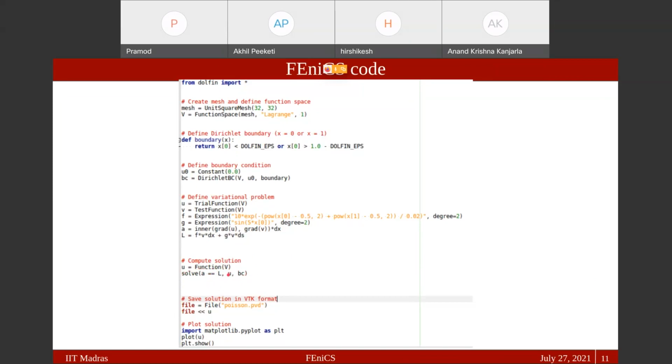So it solves. After solving, I'm creating something known as Poisson.pvd, as I said, for ParaView, for visualization. For basic things, you might ignore these, but let me complete it. So I'm opening the file Poisson.pvd, and in that I'm dumping, the process of assigning the solution to a particular file type is what I'm referring to as dumping. I'm dumping u to the file. So you will have a file known as Poisson.pvd that will have the solution u, right?